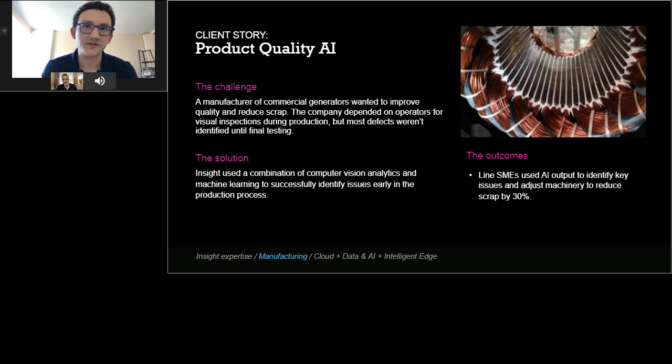Image analysis for manufacturing has existed for a while, but it's been very imperative. You've had to say, draw a line here, and does it go from dark to white to dark again? And all these very manual techniques to try and identify where the defects are. Now with machine learning, which is what we leveraged here, you can just use a data set of known good products and known faulty products, and the machine just learns. So the deployment is a lot faster to get to a solution that you can actually use versus manually having to program that.